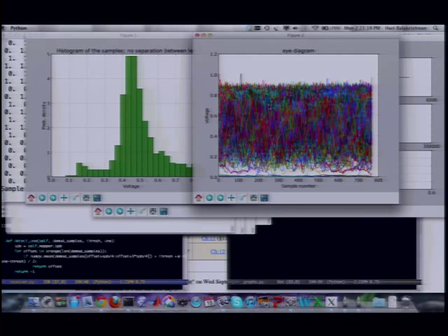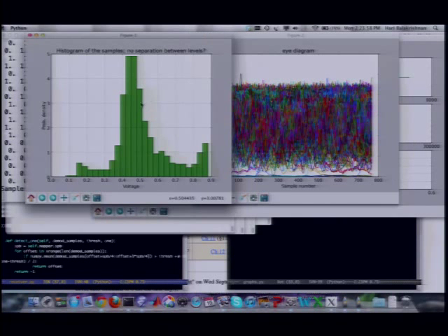This is a picture that you will become your best friend, or maybe your worst enemy. This is called an eye diagram. And it looks completely messed up. So I'm going to show you what that is, and we're going to talk about it. So let me explain to you. This noise was too high. And the point here is that that's shown in this picture here, where we ended up with enough of a variation that we couldn't distinguish between zeros and ones. We sent something which had a little bit of zeros in the beginning, and then the entire one distribution was spread between 0.1 volts to 0.9 volts. The variance is extremely high.